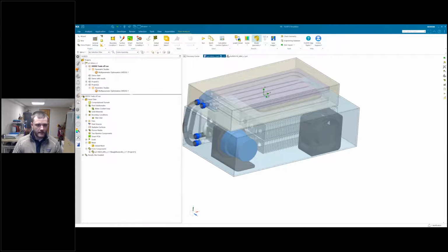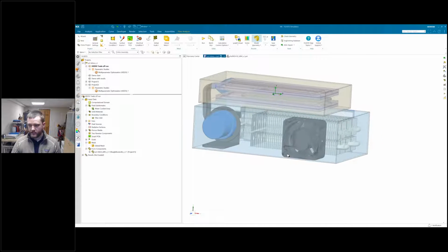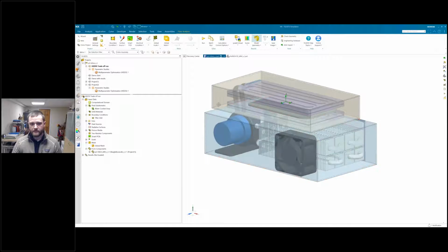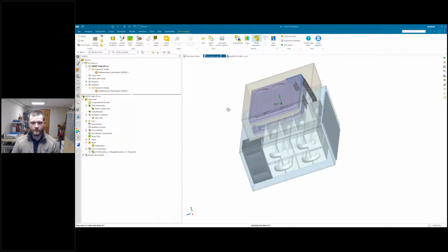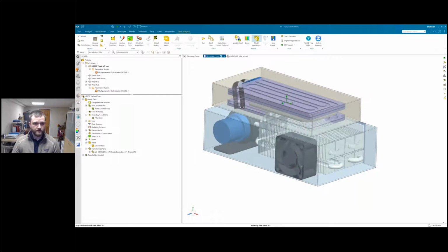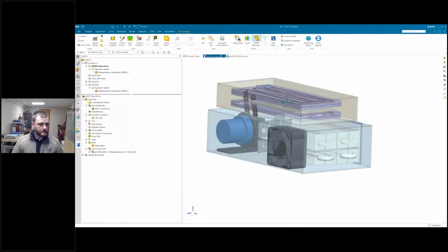But before we look at that, let's talk a little bit about the mesh that's been generated for this. And as we've said, FlowEFD uses Cartesian immersive meshing, and it still solves the same Navier-Stokes equations, still looking for resolving the solution and looking at residual values within the discretized solution. And so let's look at our mesh. We still need a mesh, and we go here and just close this up. And fluid subdomains, and then we have our global mesh here. And we can edit that definition. We can do global mesh here.